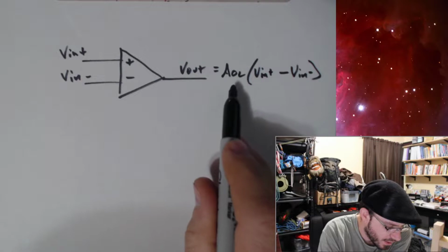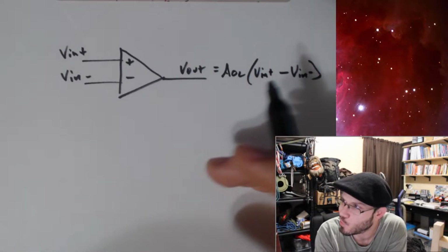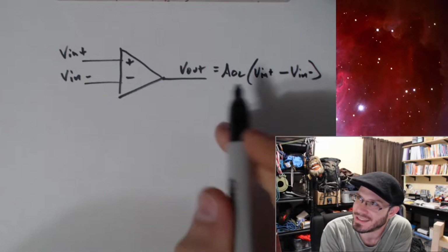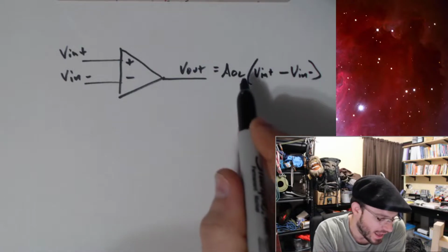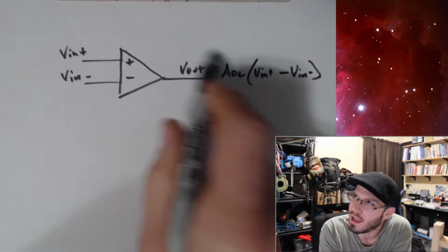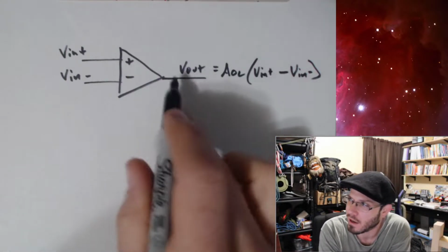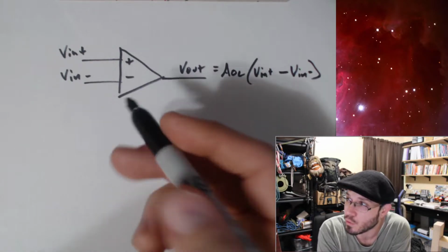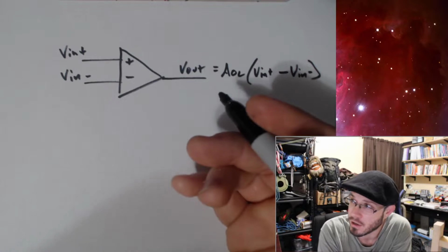However, as we already know by that asterisk mark that I had under those two rules for analyzing op-amp circuits, this value is very unwieldy. It is very large, 10,000. And so the usefulness of this op-amp as a differential amplifier is really quite limited. The only thing you could do with this is turn this into a comparator.